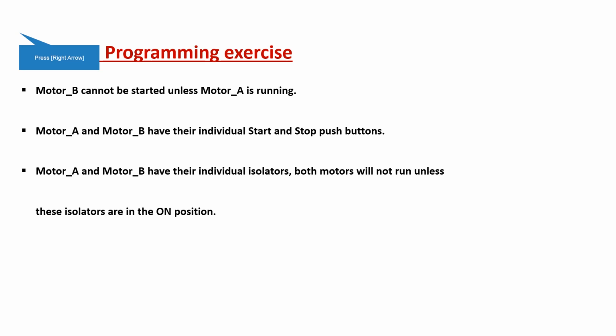These relays will be wired in such a way that they activate the contactor for these motors, so that if the relay is getting 24 volts, it's going to energize and then activate the contactor, which is now wired on the PLC panel. All right, but now depending on how you want to wire it, because it's looking at the standards.